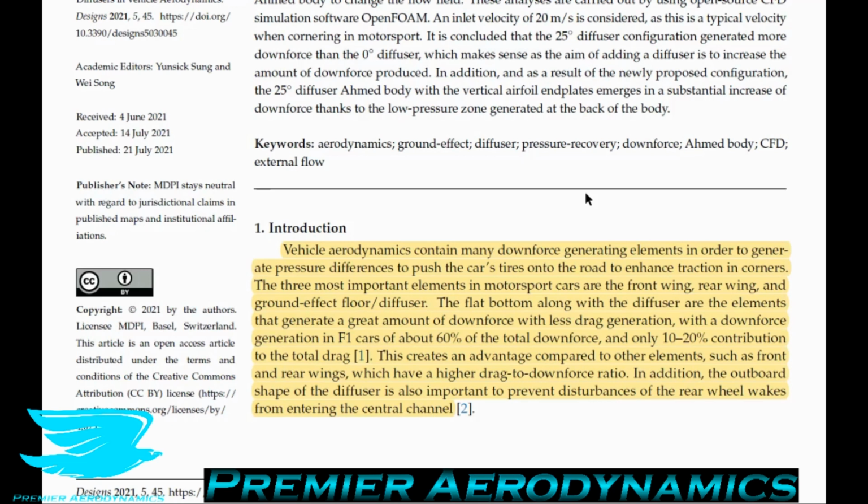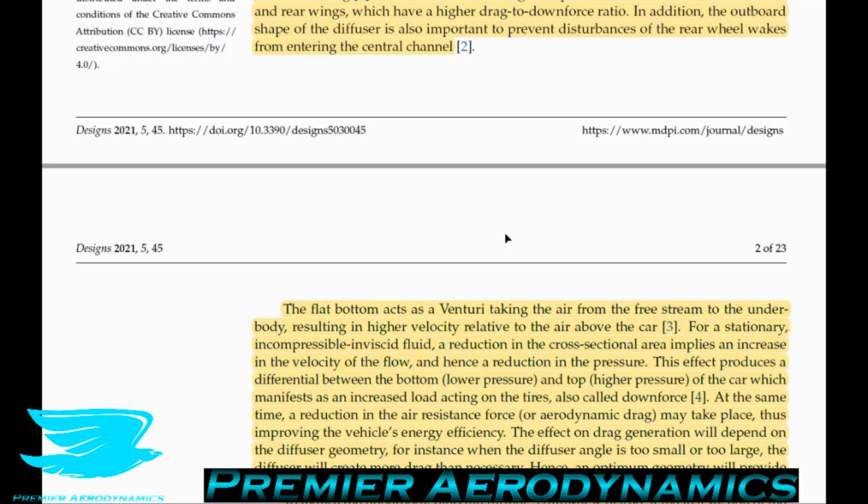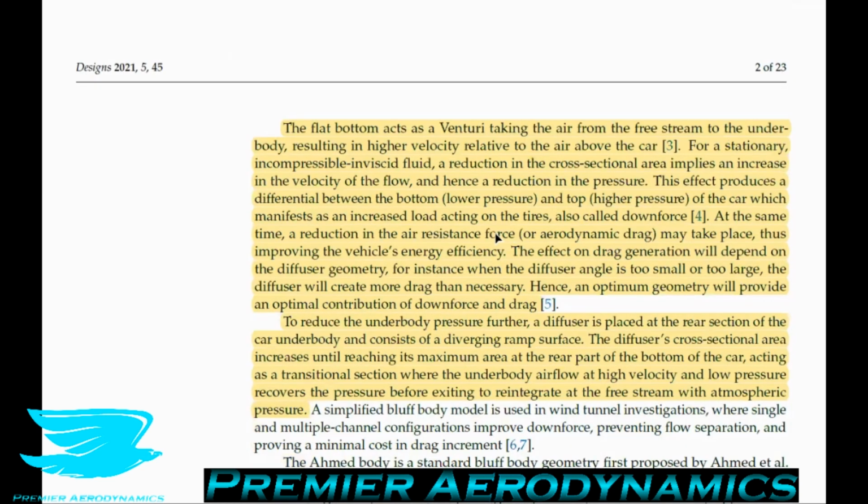And often the rear wheel air is very sluggish, I should say. And that means that it doesn't have a lot of energy, which potentially will reduce the efficiency of a diffuser. If you can actually even design a diffuser to handle these things to begin with, you may even get to the point where it just completely ruins the diffuser's efficiency, because the vortices coming off of it and the slow moving flow don't work properly.